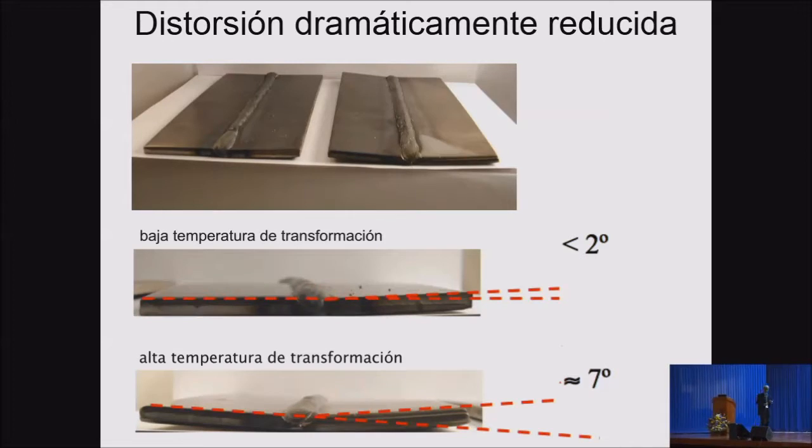Okay, so the principle now of designing a welding alloy which will cancel residual stress is well established, and we can even do multi-run welds. That means not a single bead, but several beads, by ensuring that the interpass temperature is such that the whole weld transforms at the same time. So everything remains austenitic until you've completed the welding process. And that has been demonstrated.